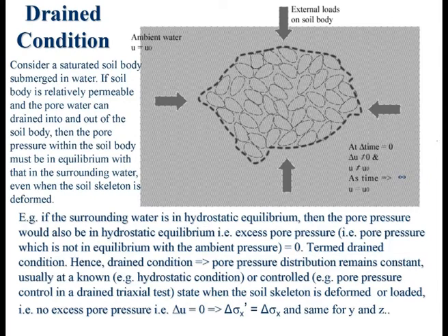Now, when we run finite element, and this is one of the things that I always remind people, when you run finite element in a drained condition, always pay attention to your pore pressure boundary condition, because you must equilibrate it to the surrounding. So the question is, what exactly are you equilibrating it to? You have to define the surrounding. Maybe it is a seepage condition, maybe it's hydrostatic, maybe it's something else, I do not know. But whatever it is, you've got to define it. This is something you must take into account.